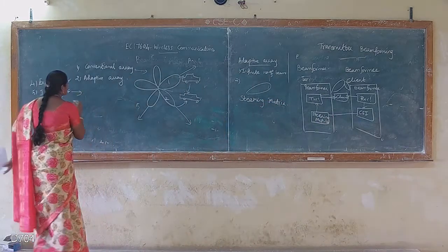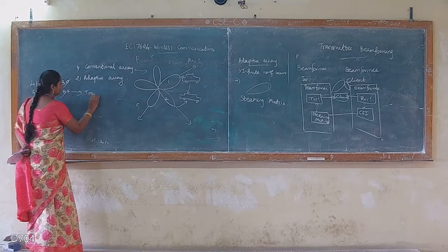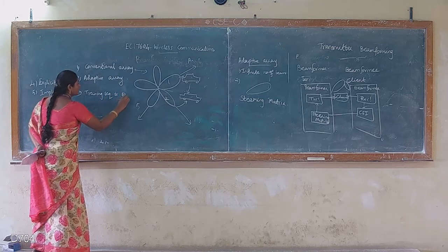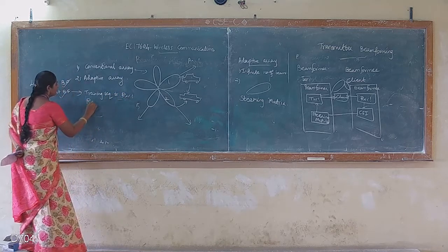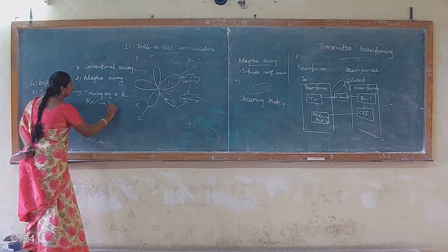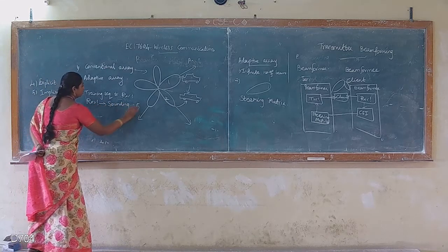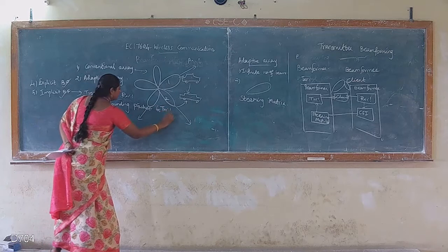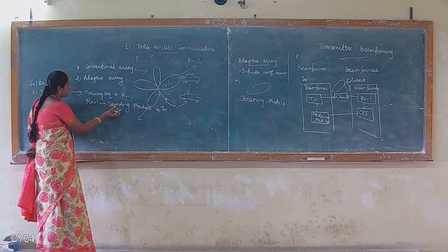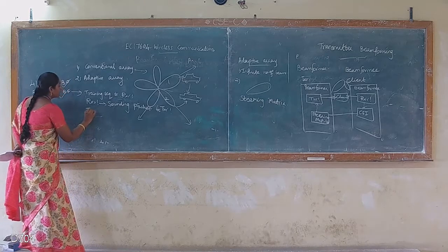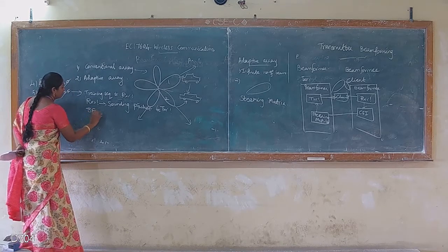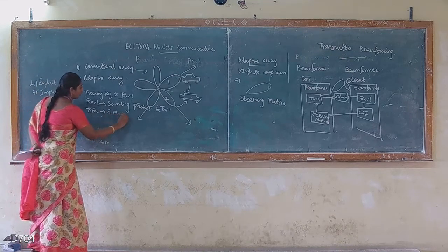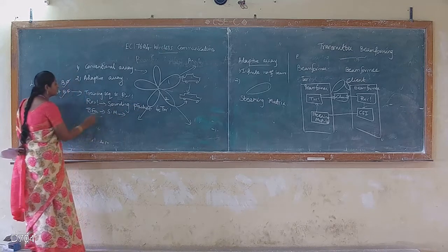What is the principle of implicit beamforming? The transmitter transmits the training sequence to the receiver. Now the receiver sends some sounding packet to the transmitter. It carries some partial information about the channel. Using that information, the transmitter or beamformer calculates the steering matrix. Using this matrix, the transmitter forms the beam. So this is about implicit.